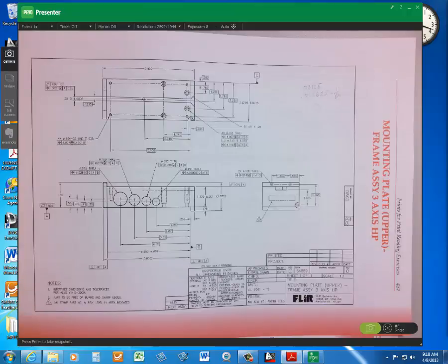Now, occasionally we might have a counterbore and put a standard old hex head bolt down in there. But if you do that, the counterbore has to be very large, because you have to allow room for the socket to fit in there and have room to play.